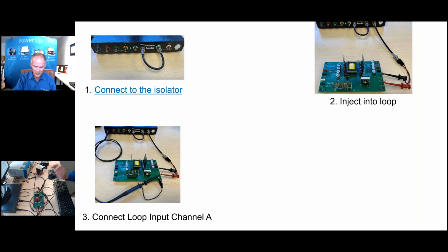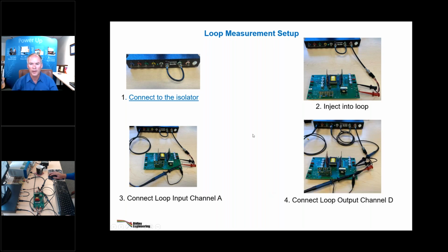The hardest part is to put the resistor into the board and put the test points into the board. Okay. Those of you who call us for consulting work, and you want a loop gain, your bill will be lower if you have an injection resistor on the board, and we'll probably blow up less of your boards too. So think about putting that in there.